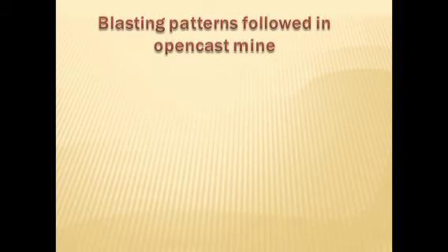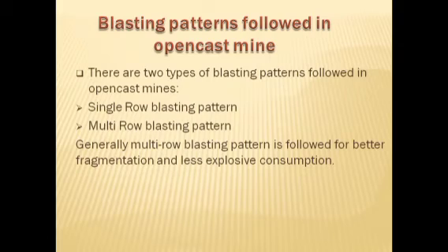Blasting parameters followed in open cast mines. There are two types: single row blasting and multi-row blasting. Generally, the multi-row blasting parameter is followed for better fragmentation and less explosive consumption.